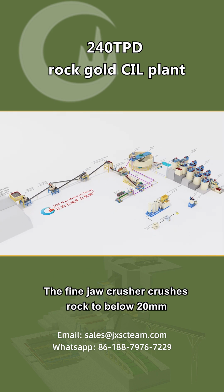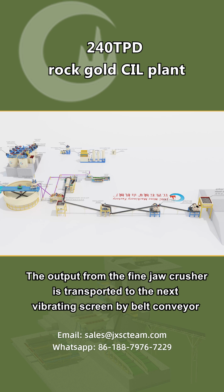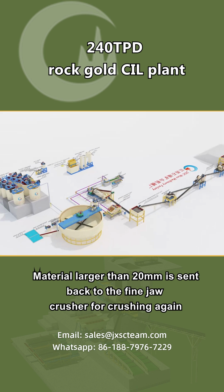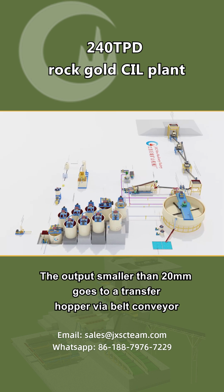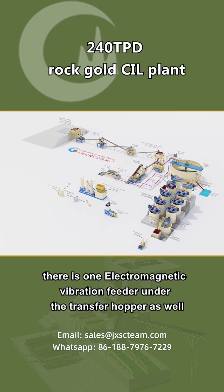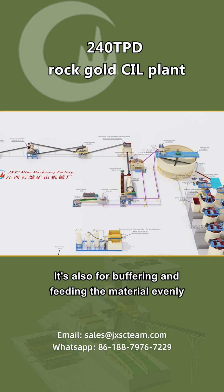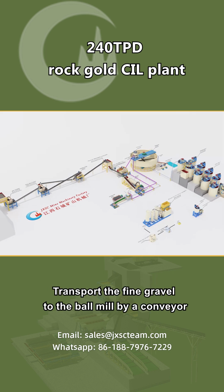The fine jaw crusher crushes rock to below 20 millimeters. The output from the fine jaw crusher is transported to the next vibrating screen by belt conveyor. Material larger than 20 millimeters is sent back to the fine jaw crusher for crushing again. The output smaller than 20 millimeters goes to a transfer hopper via belt conveyor. There is one electromagnetic vibration feeder under the transfer hopper as well. It's also for buffering and feeding the material evenly. Transport the fine gravel to the ball mill by a conveyor.